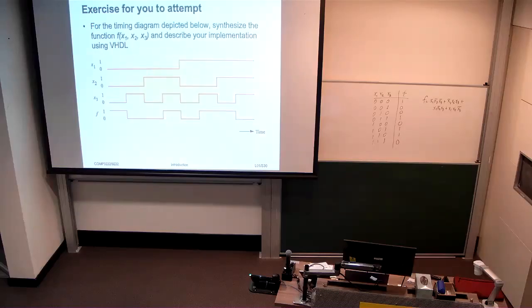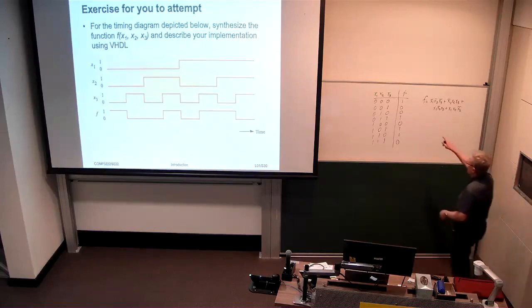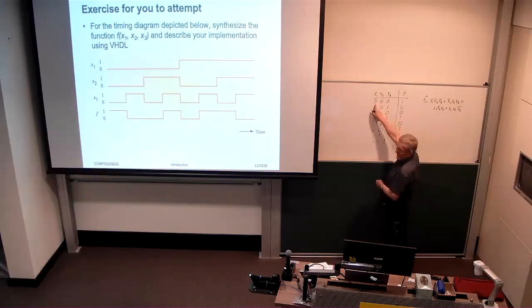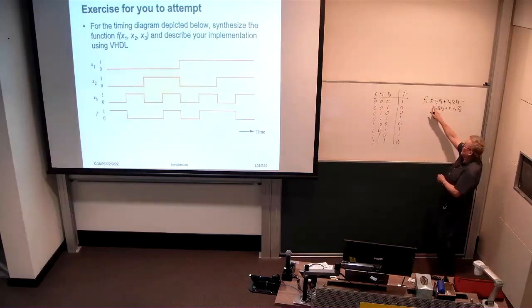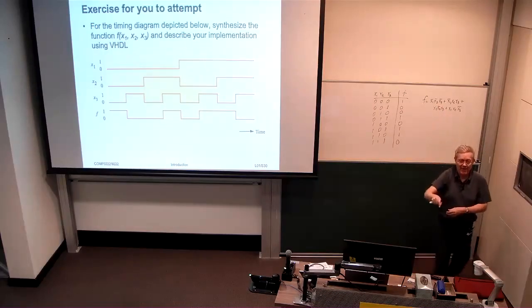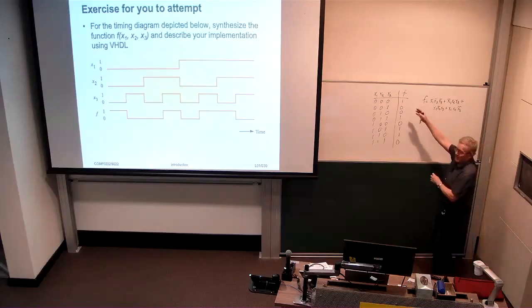So that's a logic function, and we'll talk in the next lecture about how we would normally do that. When you're writing out, if you put f being 0... Because only when x1's 0 would not x1 be 1. So I need all of these three to be 1 before that whole term is 1. Okay, and that represents one of the ones in my table.